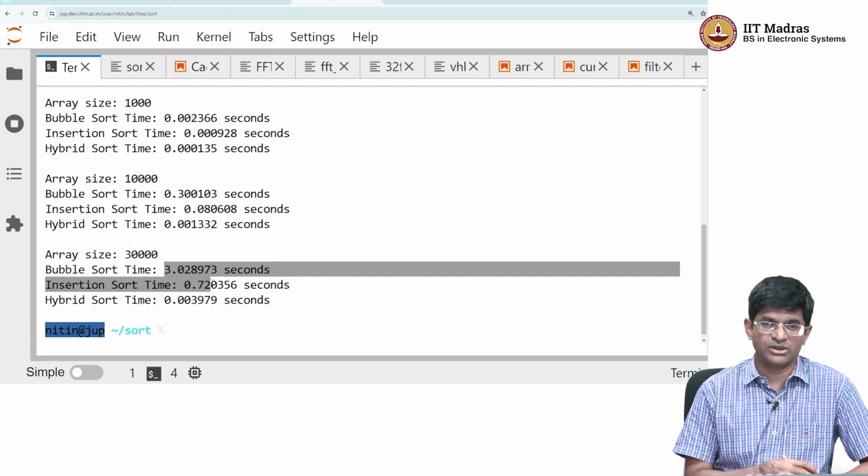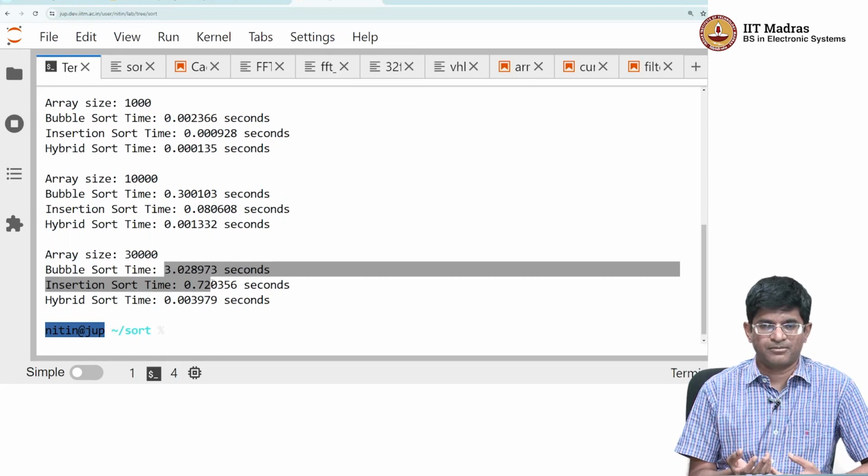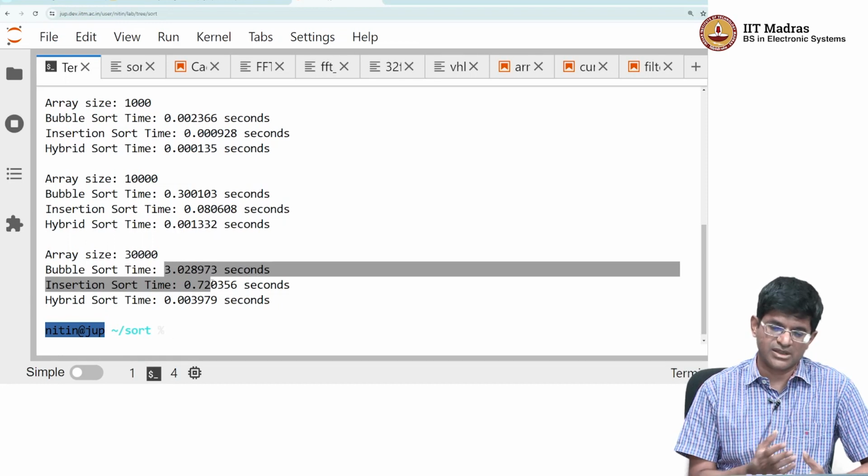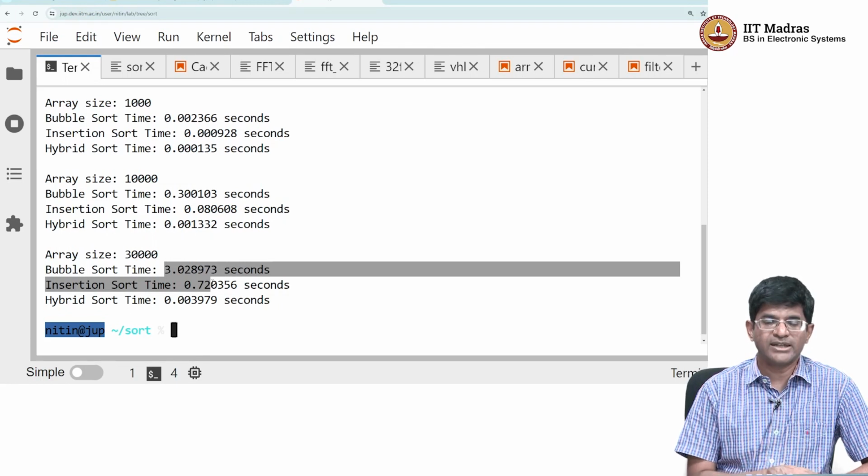Now, there is a secondary aspect to this which is not so obvious, but actually does play an important role, which is it's not just about the time, right? What is also happening over here is there are computations, comparisons, and memory accesses, both of which consume energy. Every value that is loaded from memory into a register or taken from a register and stored back into memory involves activating the bus, activating a whole bunch of pins for communicating with the outside memory, transferring data, which involves switching of various wires from 0 to VDD and back. And if you are able to reduce the number of memory accesses, which in turn of course translates into reduced time, you do get a reduction in the amount of power being consumed by the system as well.